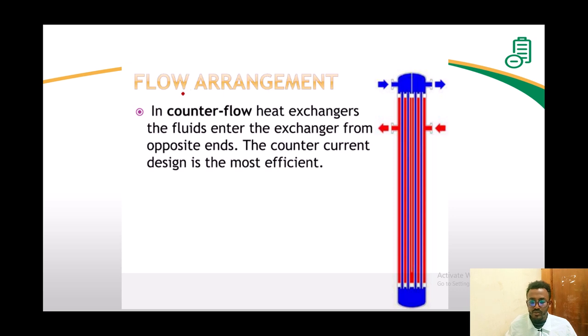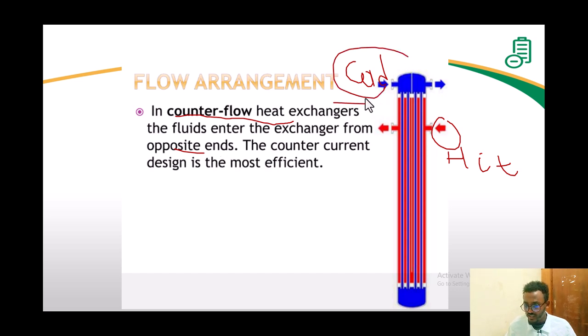And now, also based on flow arrangement, let's see the counter flow heat exchanger. In a counter flow heat exchanger, the fluids enter the exchanger from opposite sides. As you can see here, this one is the hot fluid, this one is the cold, right? They enter the exchanger from opposite ends. This one enters right here, and at the other end this one enters right here. So we call this a counter flow heat exchanger. The counter current design is the most efficient. It has its own reasons. We will see them later, how we can select or prefer the most efficient heat exchanger system.